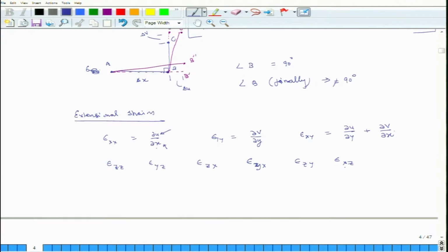Okay. So, strain tensor epsilon xx is nothing but very small change in displacement when a very small line of length delta x is becoming longer in the x direction only. Okay. So, it is associated with 2 directions, direction of displacement and direction of the original line element. Here also it is dependent on 2 directions, direction of displacement it is y, displacement in y direction is v, and original length of the line element is in y direction.